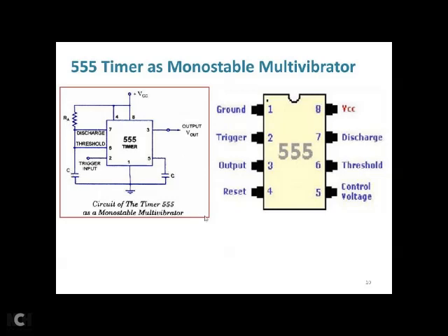We can better understand this circuit with the help of the internal architecture of the 555 timer. Before going to that, let's see that pin number 4 is connected to VCC. What is 4? 4 is the reset pin. If you have nothing to do with the reset operation in this 555 timer, you can connect it to VCC, so you cannot do any reset operation in this circuit. That is why 4 is directly connected to VCC, as we discussed earlier.